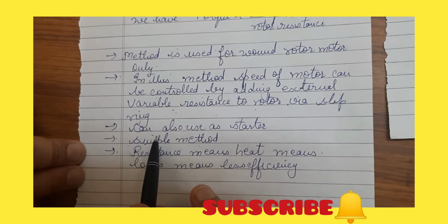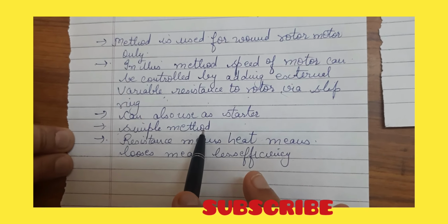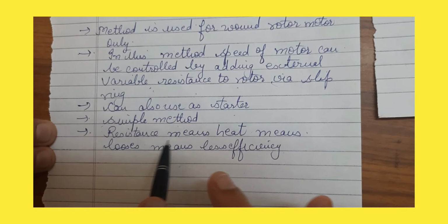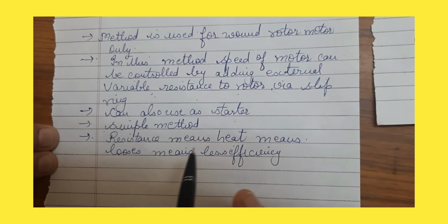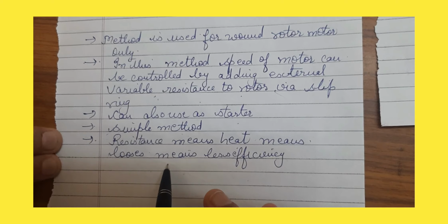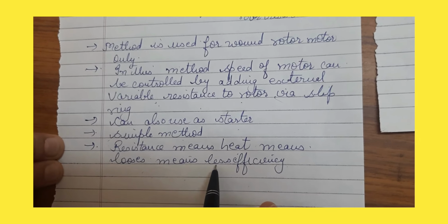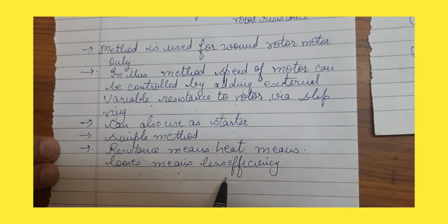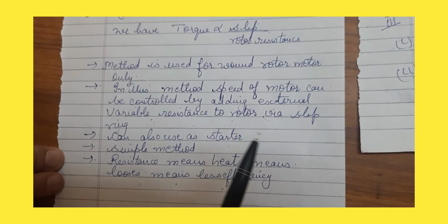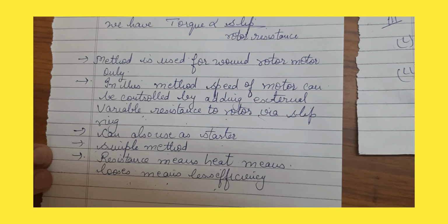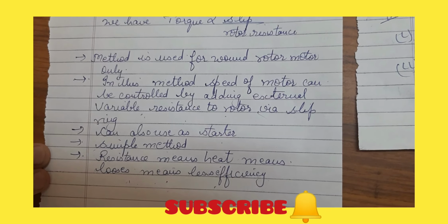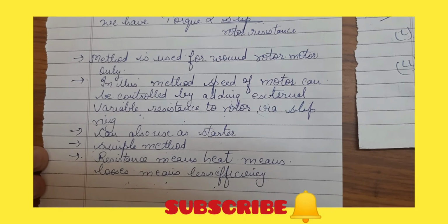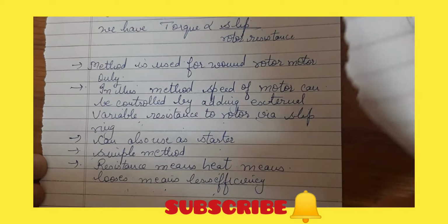It can also be used as a starter. It is a simple method. But resistance means heat and heat means losses, and if any motor produces losses, it means that it is less efficient. That is why we use this method very rarely. This is all about this topic and all about chapter 6, that is motor.